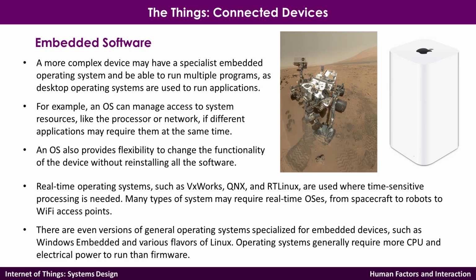Previously, I briefly discussed operating systems within embedded hardware. That is an option, but you are most likely to see embedded hardware without any operating system. But if the device is very complicated and specialized, it may contain some type of real-time operating system which allows you to manage system resources like the processor, the networking, and other input and output.